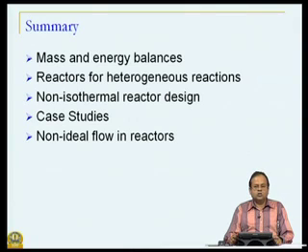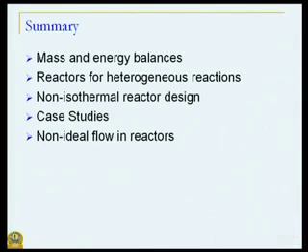And based on this, we had different types of models. For example, if we say that diffusional limitations are not there, then the rate of those disappearance processes is the same as the reaction rate. Therefore, we had a pseudo homogeneous model. This model is very similar to the homogeneous model, that is, empty reactor models, except there is a void fraction term which appears.